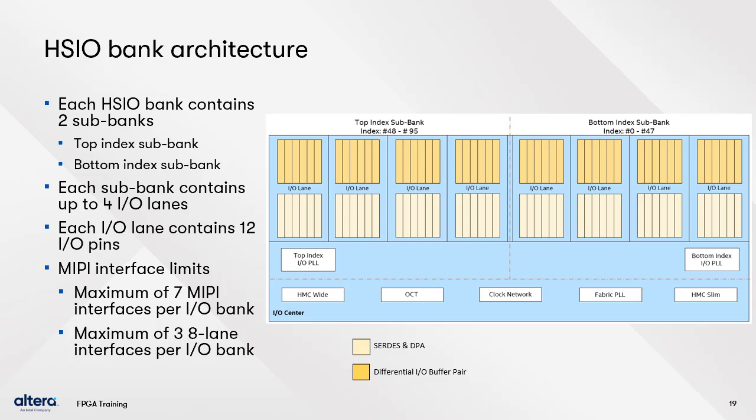The pin indices indicate relative locations within the I/O bank. These pin indices map to the FPGA physical I/O pins. See the device user guide to learn the index to pin mapping for your target FPGA.